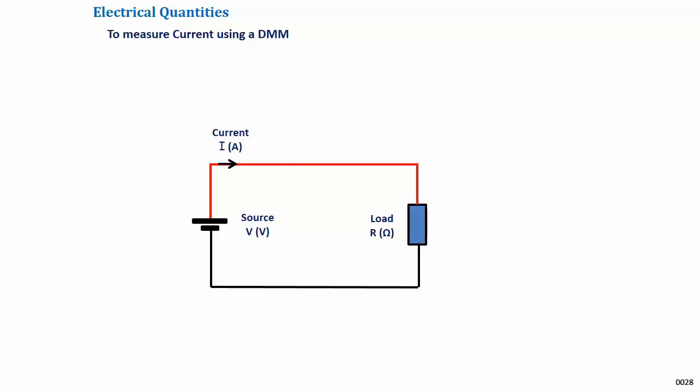Measuring current is not generally a simple process, as we have to redirect the flow of charge through the DMM. This means that the circuit under investigation has to be broken and reconnected through the meter. The DMM should be set to read DC current, and the probes located with the red in the A socket and the black in the COM socket.